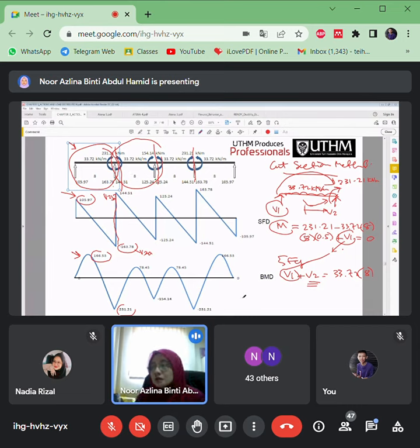Okay, so if I do the second span, earlier we used V2A, so maybe this is V2B, this is V3A. So it has two end moments here, 231.21 and this is 154.14.